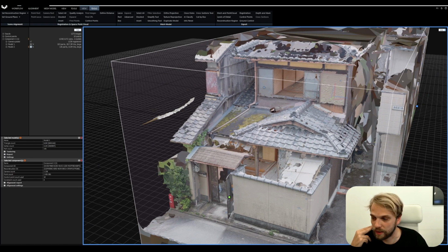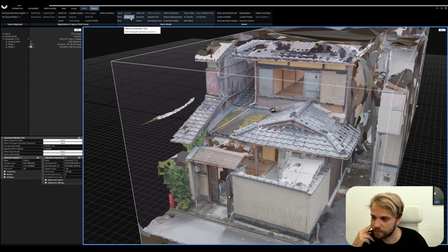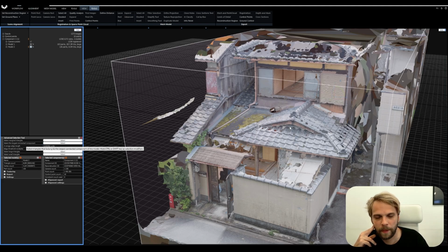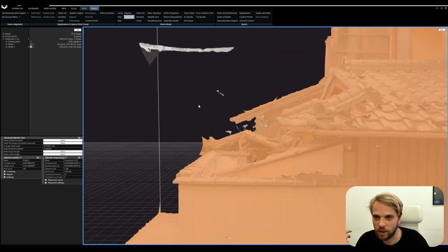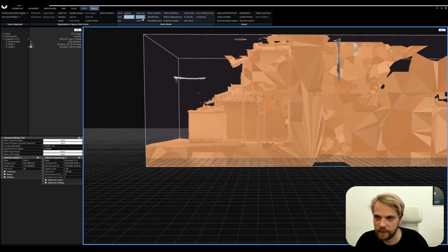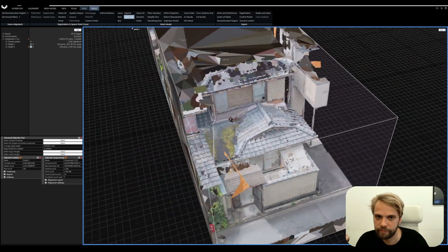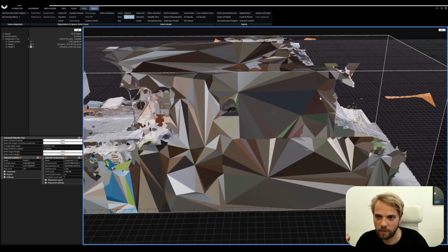The way we can clean this up is by simply going to Scene 3D tools, that's the advanced selection tool right there. And then here I simply choose, where is it? Select the largest connected component. Select it. Bam, this gets selected. You can see that all of the small bits and pieces are not selected. So what I do then is I just invert it, right? So a bunch of small stuff is selected.